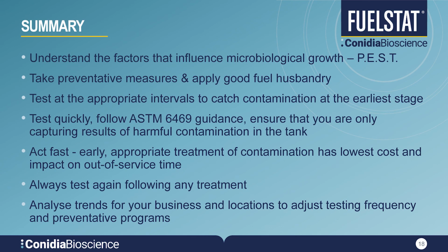Let's take a moment to summarize some key takeaways from today's session. The presence of water should be minimized as much as possible. The preparation of a fuel sample and testing it quickly is key in providing the best foundation for any test process in order for that test to do its job effectively. Good fuel husbandry will save you money by reducing unplanned maintenance costs. Testing at the earliest stage is the most cost-effective first line of defense in the fight against microbiological contamination. Analyzing trends enables swifter action and asset control.